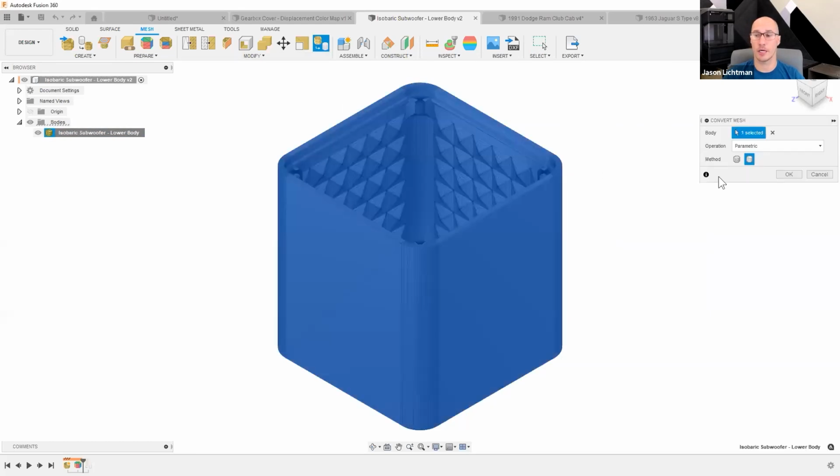I'm going to go and convert the mesh using the parametric. I could also choose base feature, which is really direct editing. I'm going to choose faceted, and it's going to create a face for every single triangle that was in this model. And by that, I mean, for every facet, those 72,100 and something facets in the model, I'm now going to have a BREP solid with just as many faces. So this flat face on the side that has two triangles will continue to have two triangles.